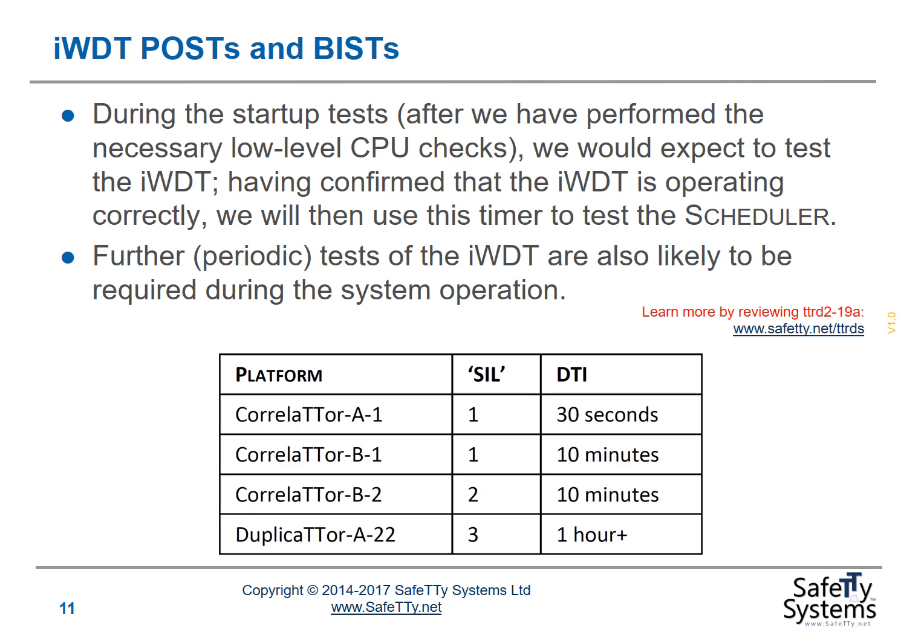The table below shows some of the diagnostic test interval figures that you may wish to use to determine how frequently you check your watchdog timer in different platforms. You can find some examples of mechanisms for performing power-on self-tests and built-in self-tests that include tests on the watchdog mechanism in TTRD2-19a. You'll find that TTRD, that time-triggered reference design, on our website.